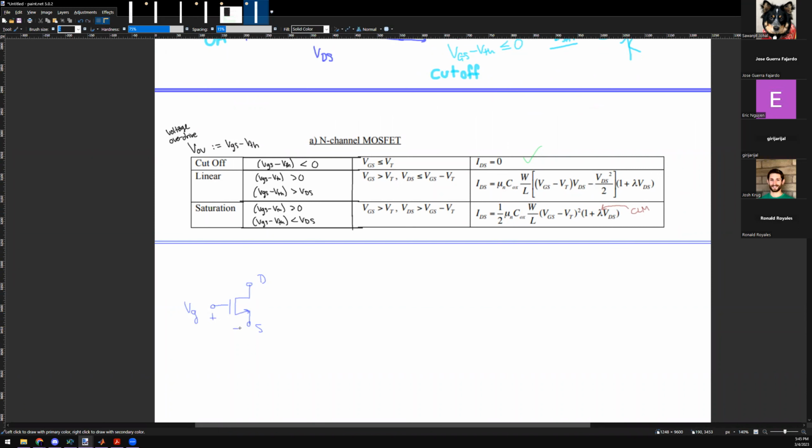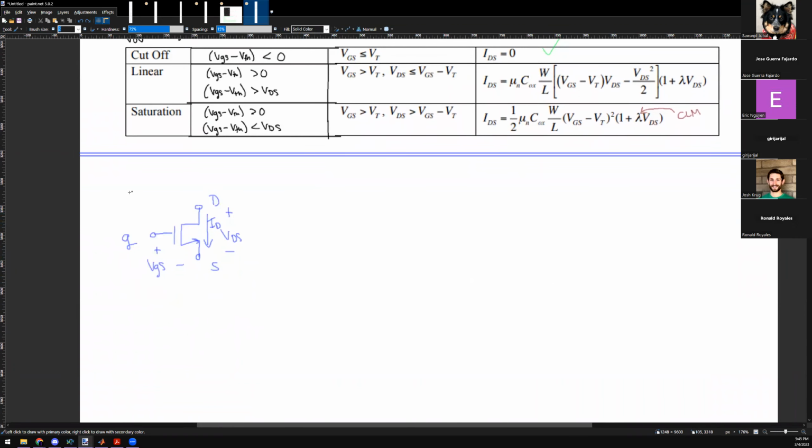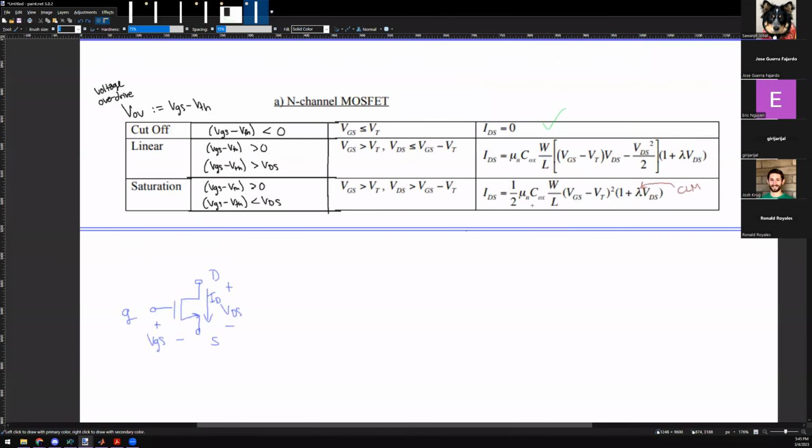So there are two main voltages in the equation modeling: there's VGS and there's VDS. And also there's this ID, that's the current that flows through it. And I want to somehow remake this guy as a linear component. So let's talk about this. This guy is not linear because of these squares.